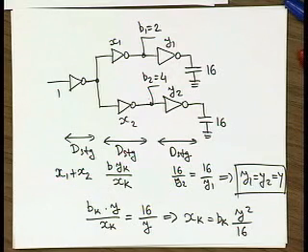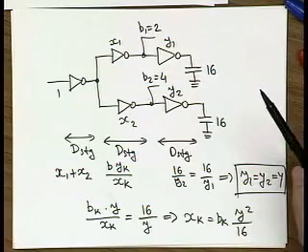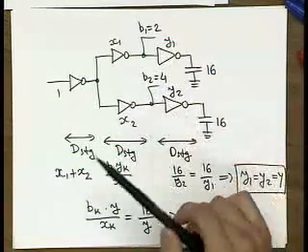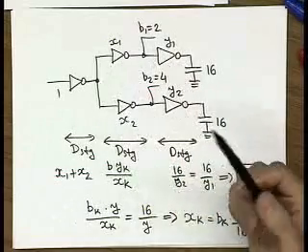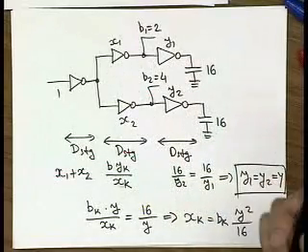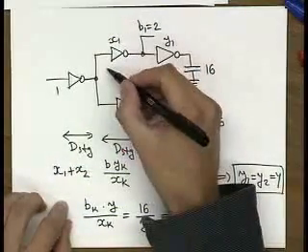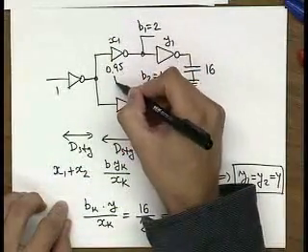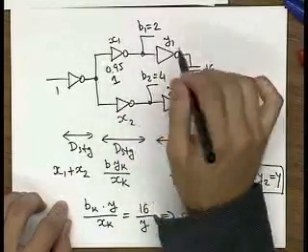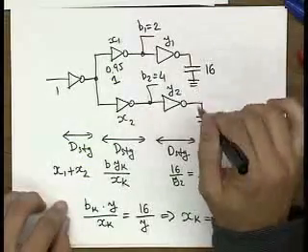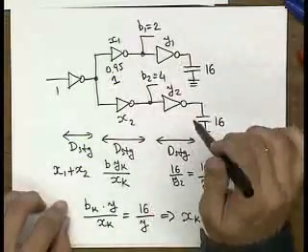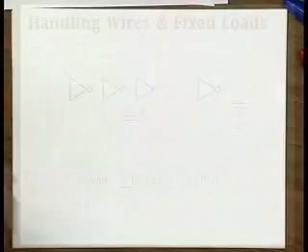Make sure also, if you write optimization programs, that you set a lower bound on the sizing of the gates. And don't be surprised if you get a slight mismatch in the stage delays, which may occur if one of the variables hits the lower bound. For example, if the optimal value for this one is 0.95, but you have to take 1, that will also impact resizing of the other gates to provide the same delay. So just make sure that you don't get surprised if you see that. Okay, good. Let's go back to slides.